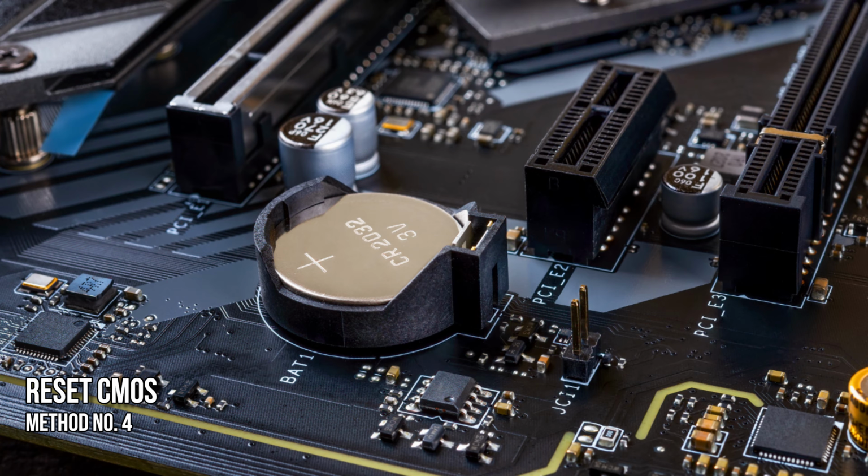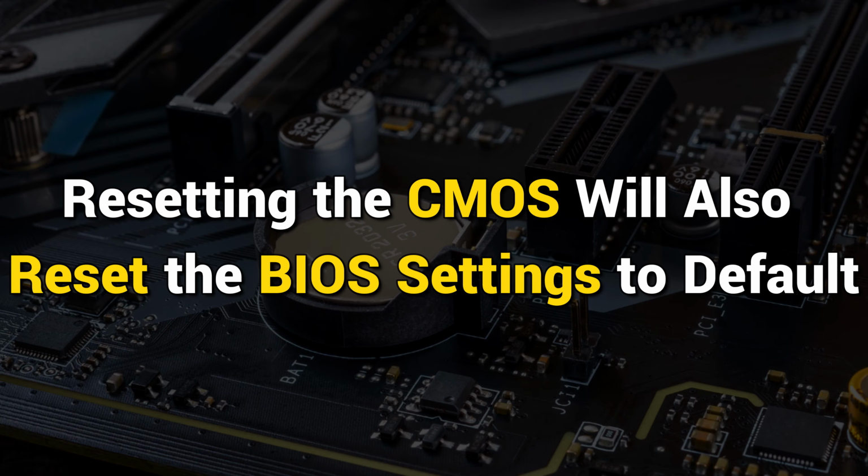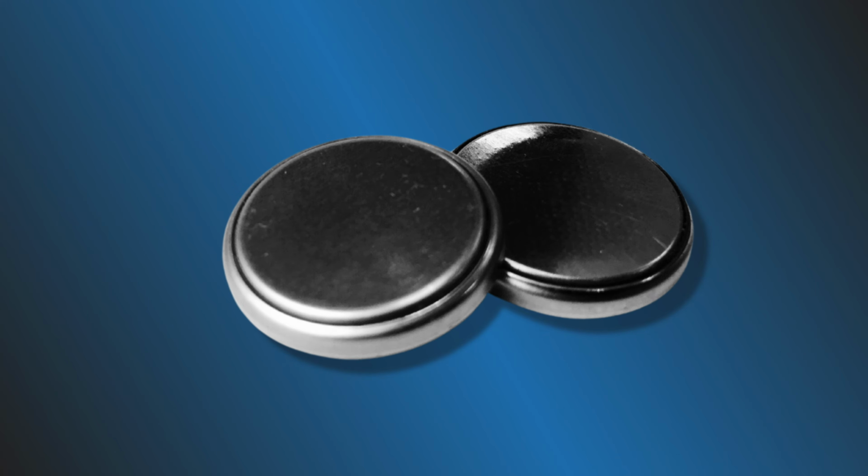Method 4. Reset CMOS. You can also reset the CMOS, a small coin-shaped battery that provides continuous power to the BIOS chip. Resetting the CMOS will also reset the BIOS settings to default. Because your display is not visible, you have to perform this action by removing the CMOS battery.